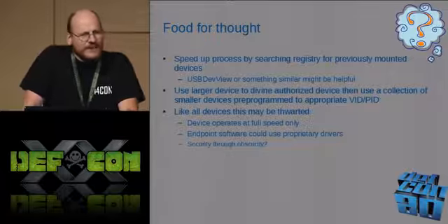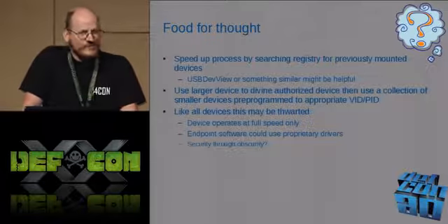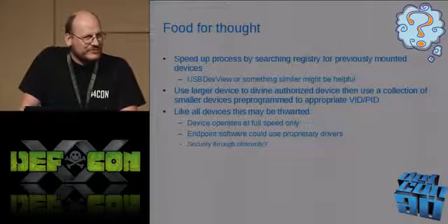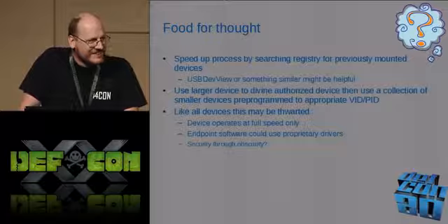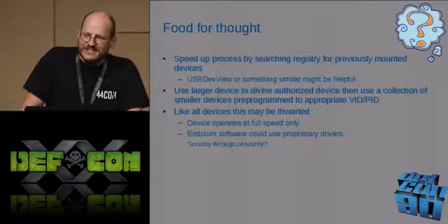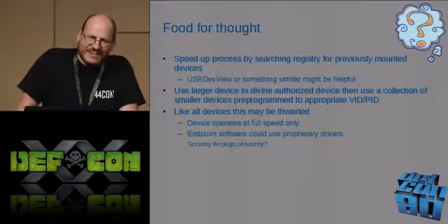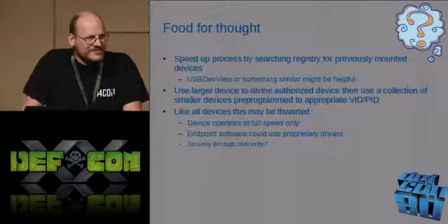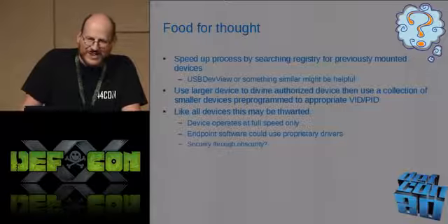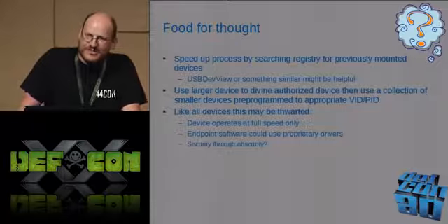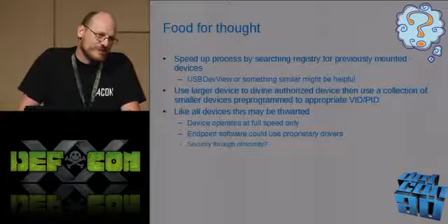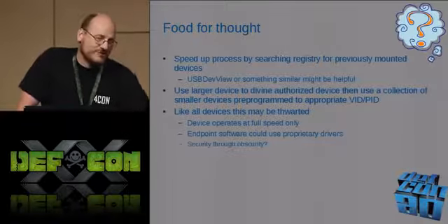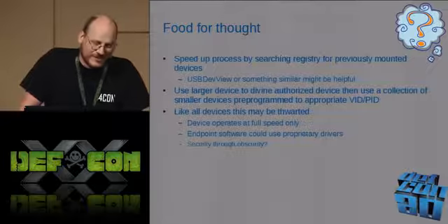One other thing, who remembers what's the maximum packet size for a full speed USB endpoint? 64 bytes. What is the default block size? 512. So what happens is it has to fragment and unfragment all those blocks. So that does give you a little bit of a performance penalty, unfortunately. But I don't know how you could do anything better other than find something that supports full speed.